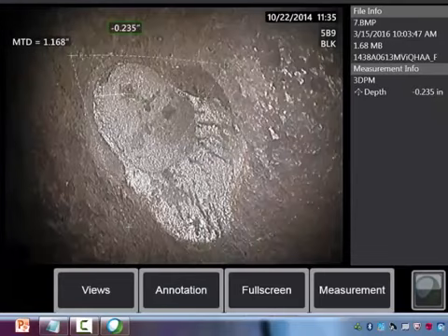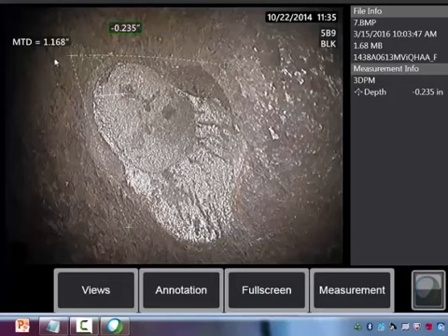All right, so for our next example, we have another 3D phase measurement image, this time inside a riser pipe, where we have a surface indication that looks like it might be some form of pitting. So we have another depth measurement here, and what we'd really like to know is the maximum depth of this indication. As we look at this 2D image, it's really hard to tell if that's what we've actually measured.